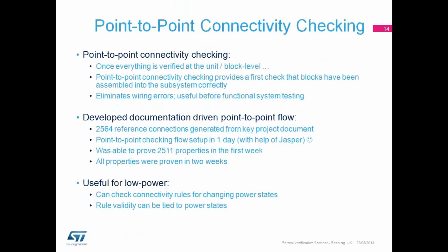Right, P2P checking. If you guys haven't looked at this, we had a very good experience using Jasper on P2P checking. Once everything's verified at unit and block level, we hand stitch it all together, and we generate effectively a golden reference of the connectivity from some of the project documentation. This is very heavily reviewed, and we can feed it into Jasper and get it to check that the RTL is in sync with the spec.